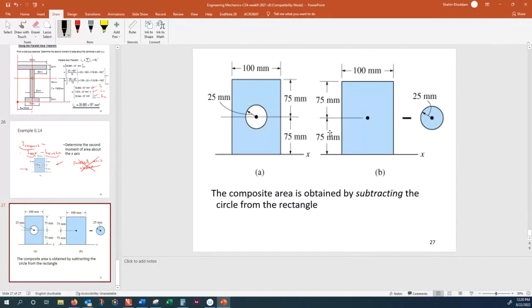In summary, today we summarized the method of equation. The method of equation is very important. You always have to start from finding reactions, developing an expression for the distributed load as a function of x, and then integration, applying the boundary conditions. Of course, you need to know how many loading zones there are, whether there are discontinuities, whether there are point loads or just distributed loads. And then we went through a number of practices.